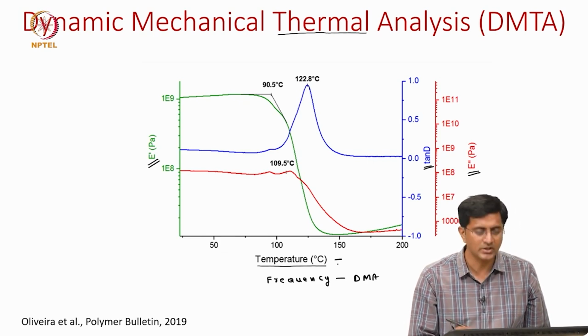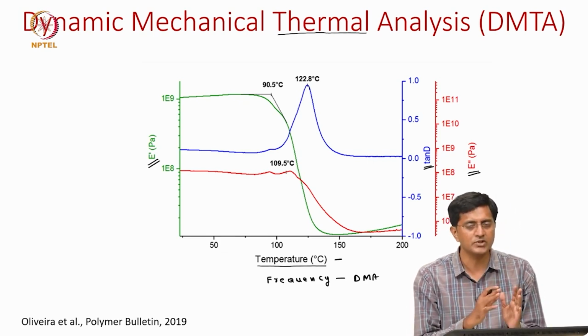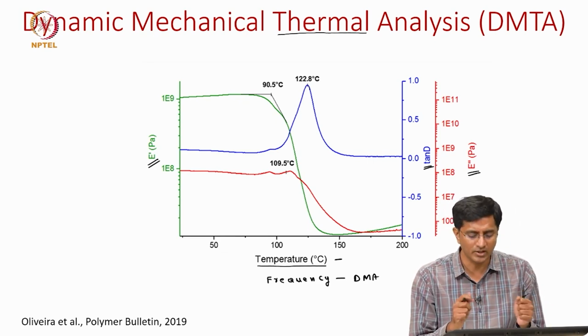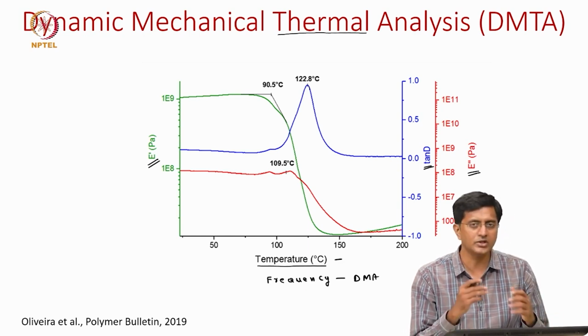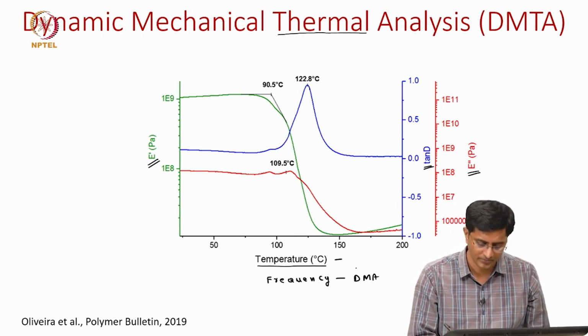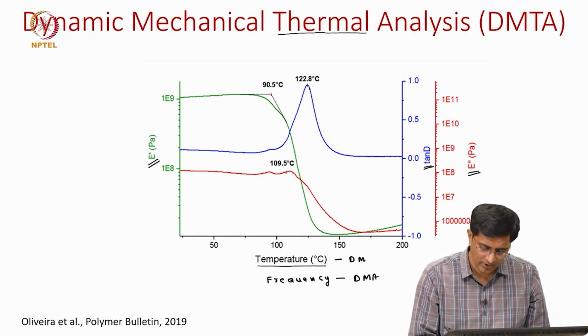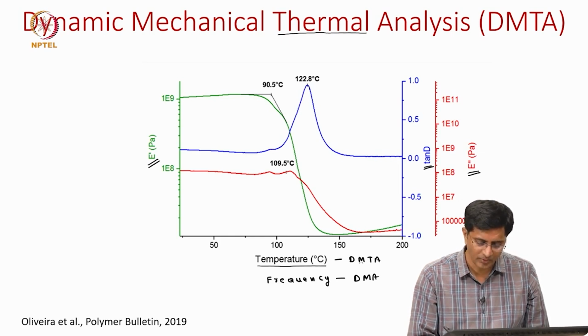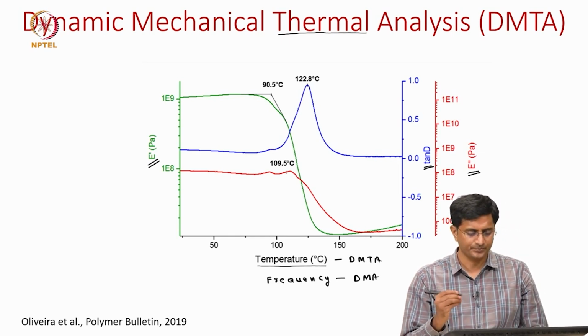Now, we keep the frequency constant, but by varying the temperature we look at how these modulus values vary, which is the DMTA, standing for dynamic mechanical thermal analysis.